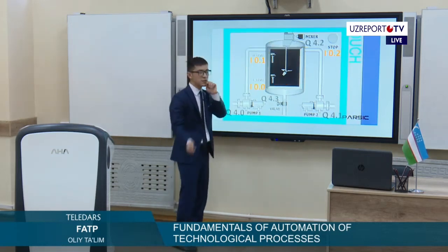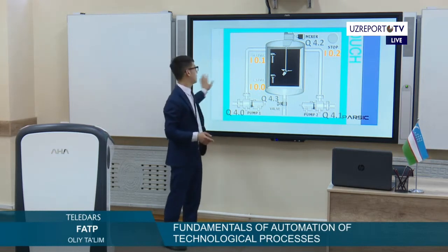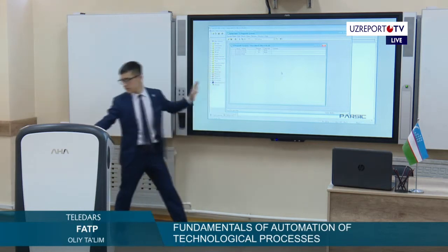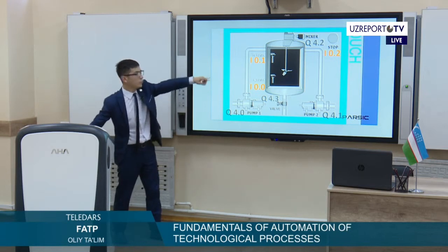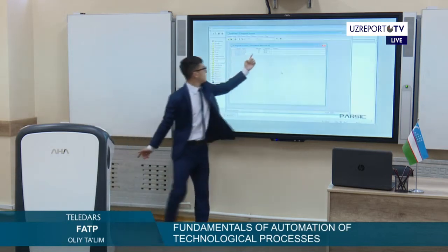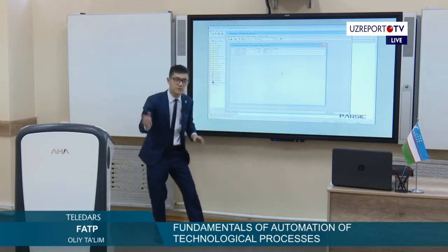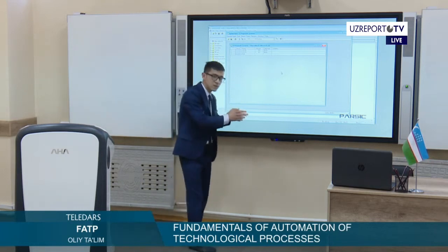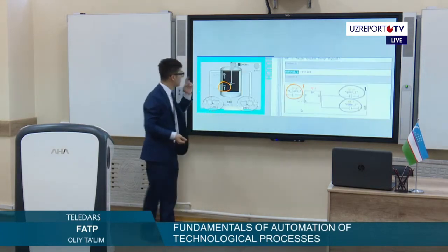We will make special names and numbers for our inputs. And then we will transfer the information which you made in this algorithm. Remember, 01, 00, 02. They will be named here in the address. In the middle side, address, and we will give the type of signal. This time we use two sensors with digital signals, so it will be bool. Then we will use the level.